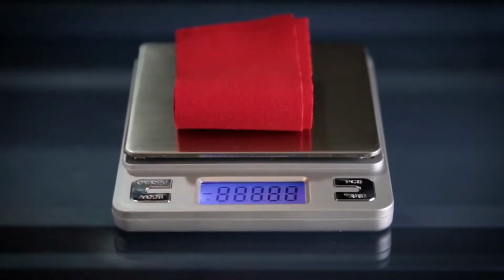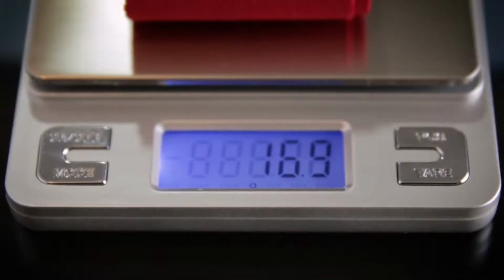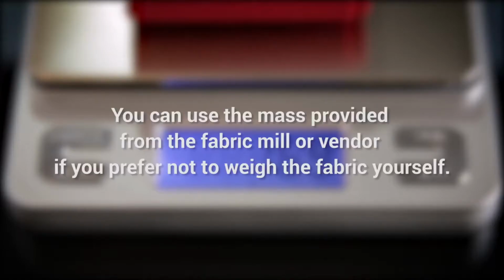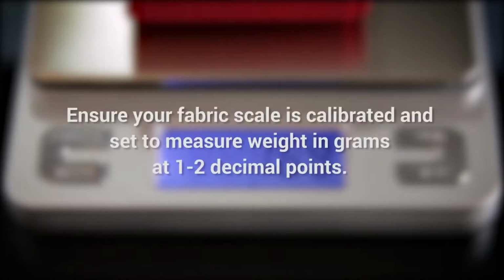Place all 3 fabric strips on the scale. Record the total weight, then calculate the average by dividing the total weight by 3. Please record this number as it will be used later in our testing process. Alternately, you can use the mass provided from the fabric mill or vendor if you prefer not to weigh the fabric yourself. Weight must be in grams per meter squared. Please note, ensure your fabric scale is calibrated and set to measure weight in grams at 1 to 2 decimal points for the most accurate results. The fabric scale is not provided by Browzwear.